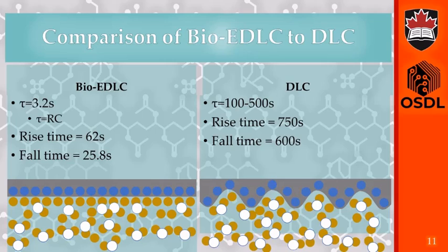DLC capacitance relies on solvent dipole charge localization due to the external field, rather than ion content or solvent choice. Bulk hydrogen bonding to adsorbed water molecules produces lower energy sp3-like bonding structures. The contest between dipole orientation and hydrogen bonded absorption results in capacitance-inducing dipoles distributed in low density. Thermal fluctuations allow more sp3-like adsorbed molecules to switch to dipole orientation, which causes local aggregation and increases the capacitance. The charging time is influenced by the expansion time of these dipole-oriented regions, rather than the device capacitance.